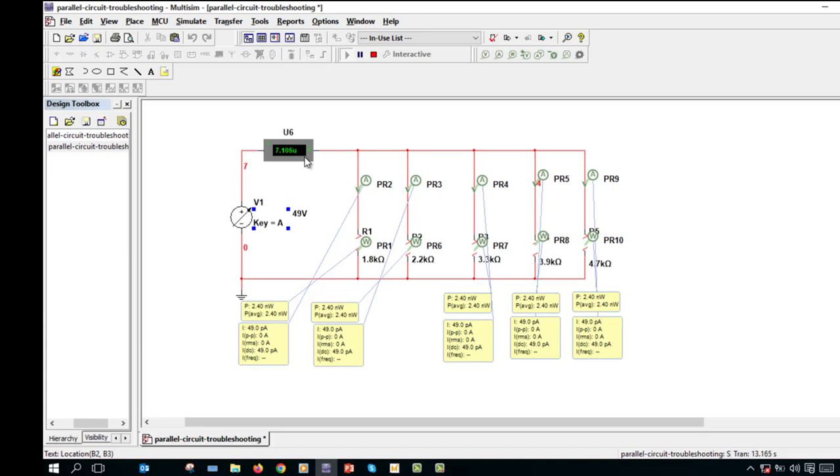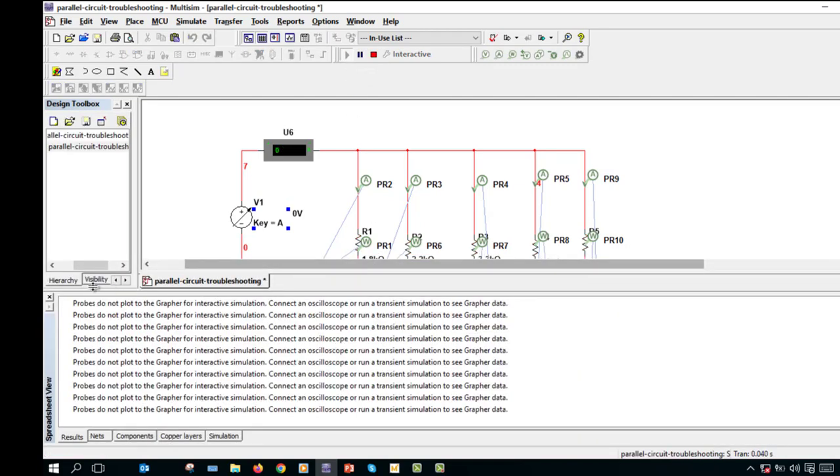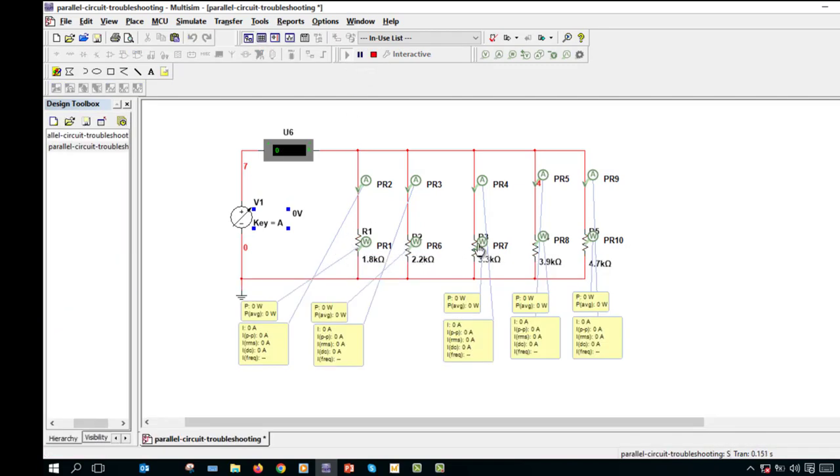So this is how we simulate or troubleshoot. You can see how the components blow up. If I say stop now and I reset this to 0, you see all these openings here. When I say run, it will come back to normal now. It has been restored. But as we increase the voltages, once it gets to that 30, it must blow up. You see, this will blow up. You see, R2 has even blown up at the same time. So that's how the rated components work.